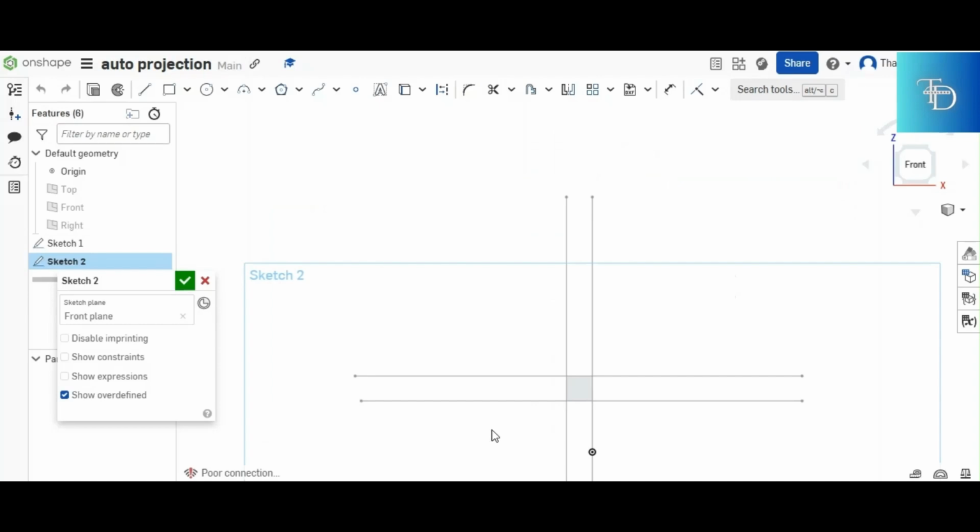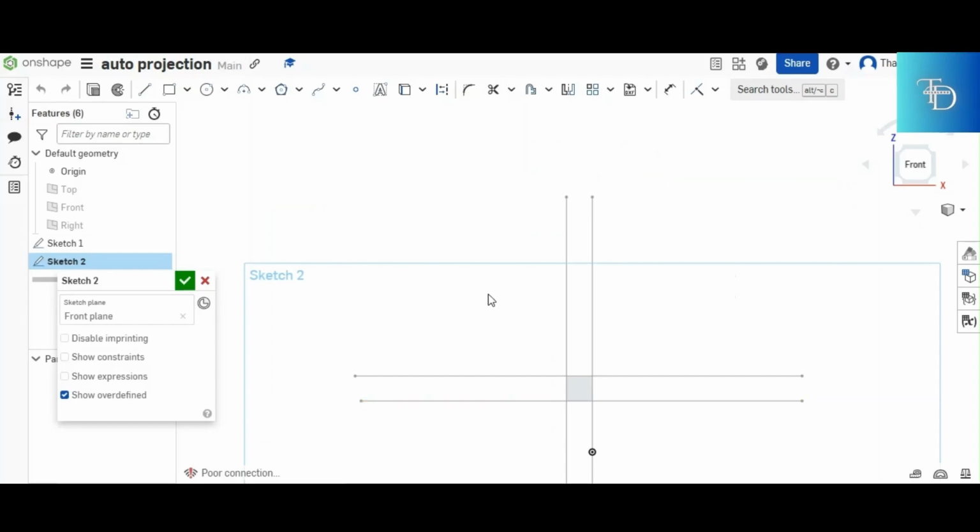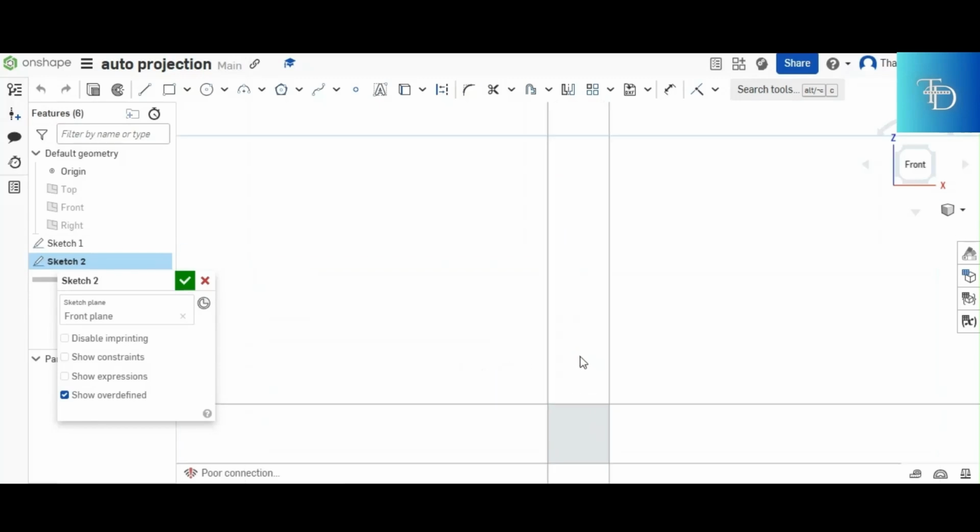So since we're gonna start with the front view, you already know now that you're gonna put your front view where? On the first quadrant. But where should it start? Should you put it anywhere along this line or anywhere along that line? No, you don't just pick and choose where to put it. Every view starts at the corner. So the bottom right corner of your front view should be right there.